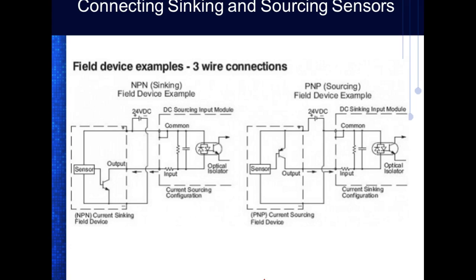Normally, you don't do that. What you do is, normally a sensor gives you one set of contacts. Some of them give you a maximum of 2. I think we got one back there. The temperature probe actually has 2. It gives you one normally open and one normally closed. Most of the time, a sensor gives you one contact, and it's usually normally open. So this doesn't even have a contact. A lot of times a PNP won't even have a contact. It literally outputs directly from the collector of the transistor.